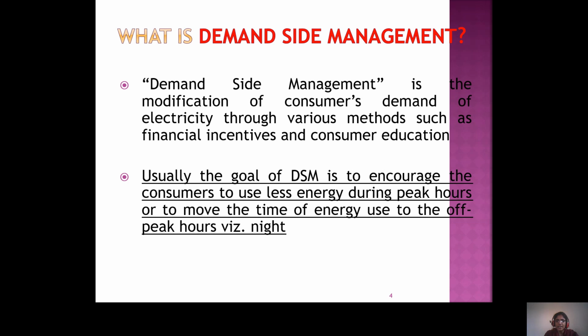So demand side management is nothing but controlling the quantity of energy. The quantity of energy used at a specific time has to be reduced to cut the system peak demand and achieve load leveling, reducing the overall system demand and balancing the system supply on demand. So demand side management has traditionally been seen as a means of reducing peak electricity demand.